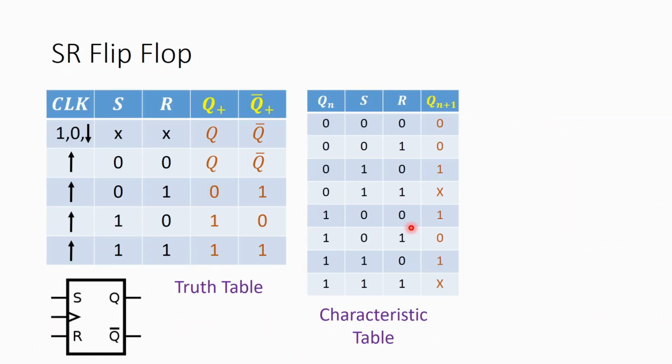So now from the truth table, here we are maintaining a positive edge trigger. However, we just need to know which edge trigger it is, and if we know that, then this column does not make any further contribution to our information or to our knowledge. Once we know whether it is positive edge trigger or negative edge trigger, then we can simply delete this column and we can start looking into these 4 columns. Okay, this is what is important.